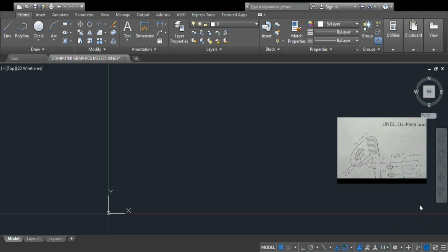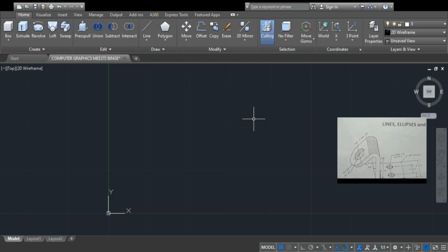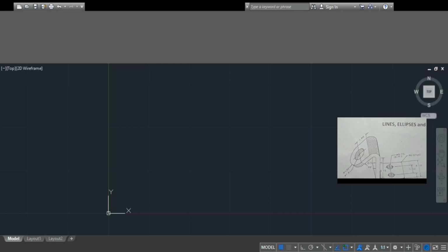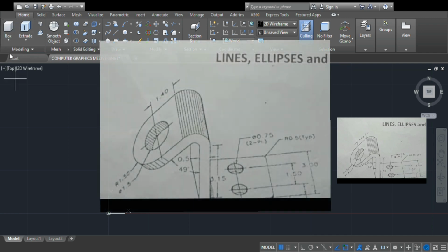Now to move to the 3D workspace, you see this gear icon on the bottom right. Click that gear icon and select 3D modeling. There's 3D modeling basics and 3D modeling. If you click 3D modeling basics, you won't get enough options, but if you take 3D modeling, you get the full options because you're a big boy now and you want to start 3D modeling.